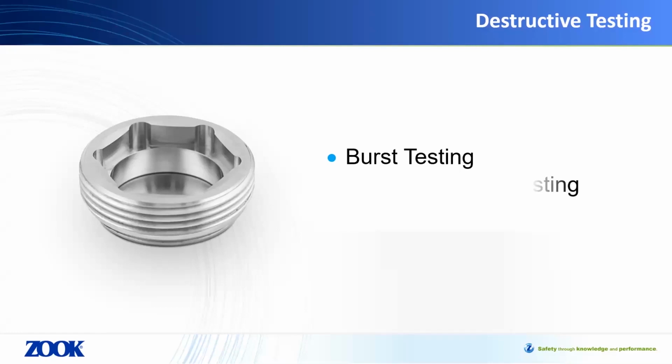As in many cases, a welded unit or cartridge becomes an integral part of the piping system both before as well as after the rupture disc is actuated. It's important to perform housing tensile testing in order to validate calculations made at the time of design regarding the ultimate strength of the component.